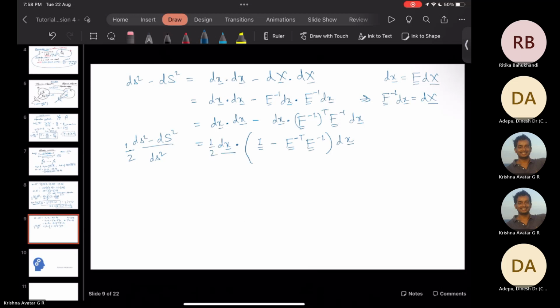So we'll have this, and this will again involve division with respect to s. I'll take half and keep it here. And this we call something known as small e. And this again is a second order tensor. And this is called the Almansi strain. Sorry, not stress, it's Almansi.